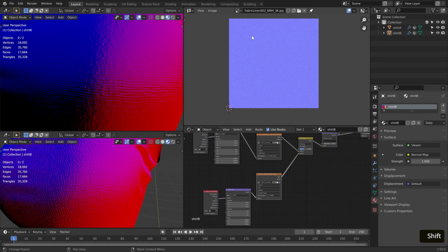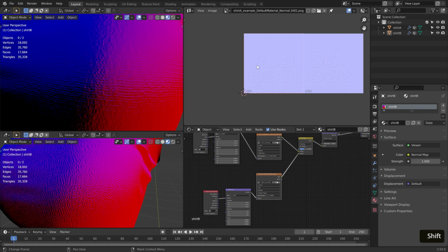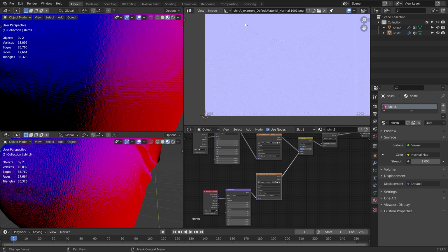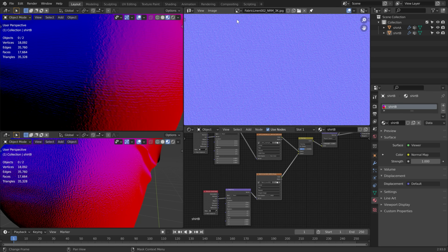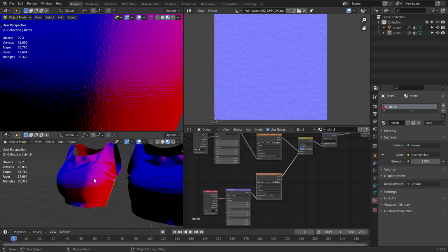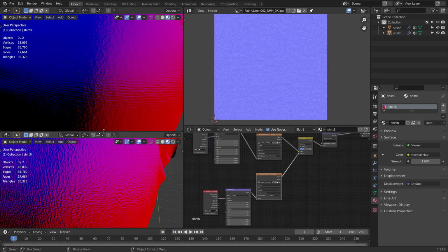The reason for this is that once you bake anything into textures, all of the color information is limited to the image size of the file. So whatever you do, if you take a 4K cloth pattern and bake it, you will lose very fine detail, which might look fine from far, but once the camera gets close, you will see the issue.